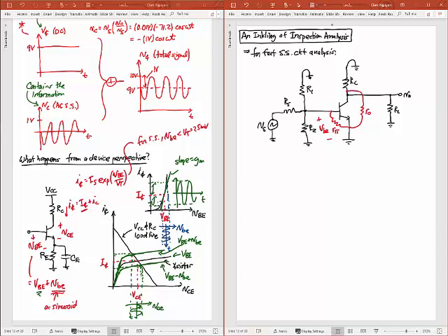I really have an R0 across that. I also have a controlled source coming across that. So I know that my collector current going through this, I sub C, is going to be gm times VBE. Okay? If you can look at the device and see what I'm showing right here, you can do things a lot faster. So let me go ahead and do this problem again, but looking at the device by the R-pi and R0, and that gm times VB is going to come into play at a certain point too.